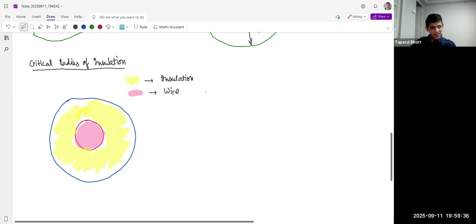But anyways, in this case, what is the Q dot, the heat transfer? The temperature here is let's say T1, and the temperature outside is T infinity. So Q dot is basically T1 minus T infinity over R insulation plus R of convection.